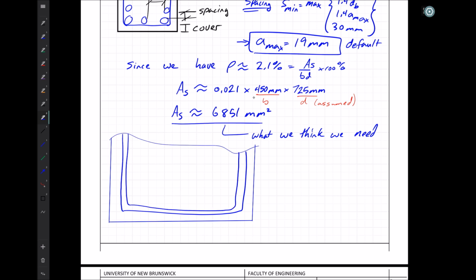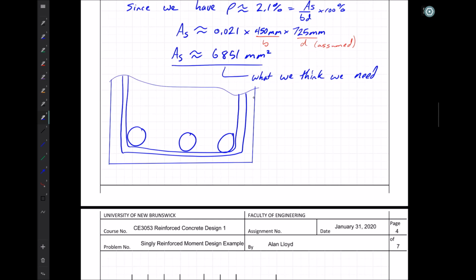And then inside of that, we're going to have whatever longitudinal rebar we have. So looking at all this, we need to measure some stuff out. First off, we can say that the outside dimension of this thing is going to be B, the width of our beam. Then we've got some stuff happening inside. We've got the distance between the edge of the beam and the outside of our 10M stirrup is BC prime as the minimum value that we're going to put there.